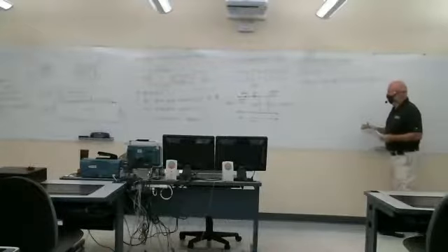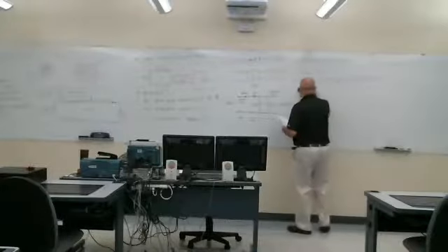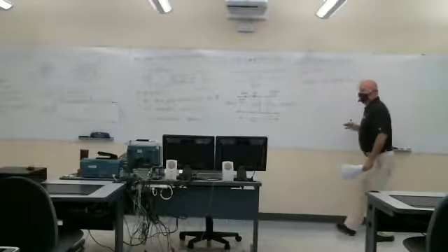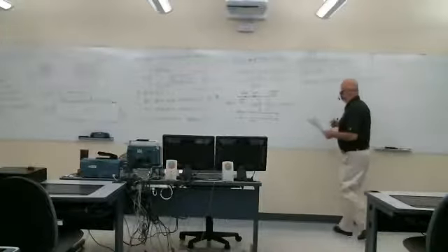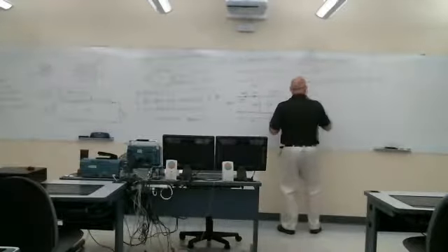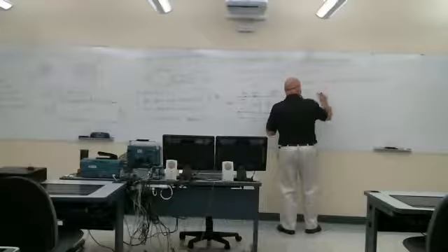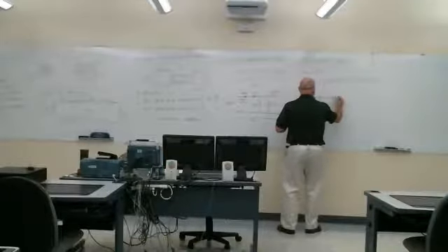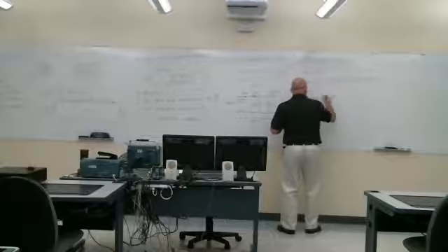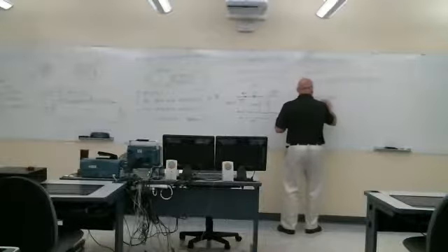So I'm going to put the voltages on one side and the currents on the other, so come up with a relationship between the voltages and currents. So I'm going to move the voltages to the other side. So I'll have V(z + delta z, t) minus V(z, t). And then I'm going to divide everything by delta z.